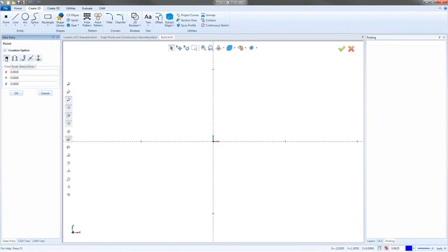So the first one would be the point sketch or enter. And then next to that, we have the point from entities. We have the point incremental, the point on an entity, and then we have that point perpendicular function. So what's cool about this is our development team combined a lot of the functionality that we have inside the system. So when we go into point now, it's not just a point coordinate or a point sketch. It now does both. You'll also notice there's no snap functions on anything because now this can be used to snap as well.